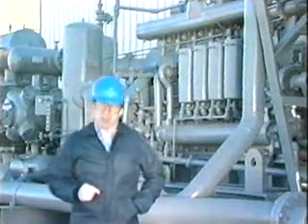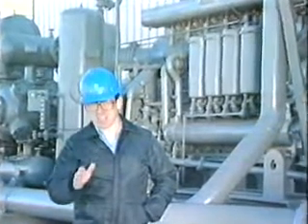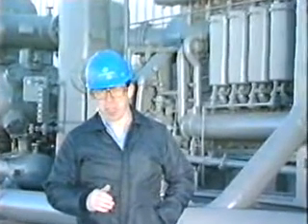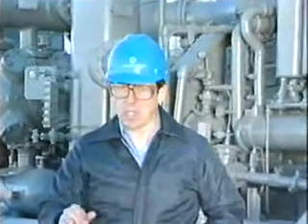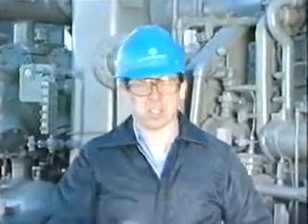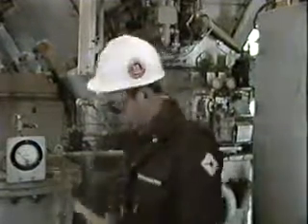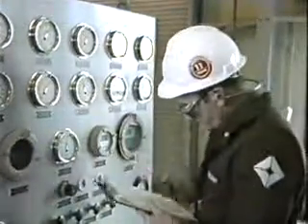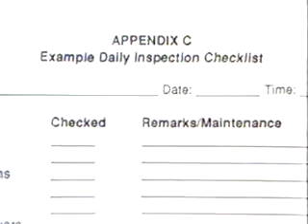Now, as an operator, it is vitally important that you pay close attention to the gauges and sight glasses that monitor your compressor package. Finding an operational problem early will go a long way toward maintaining a safe and efficient unit. And so will daily inspections. A compressor package requires at least a daily inspection to ensure continued smooth operation. It's a good idea to have a checklist to make sure all the inspection points are covered.